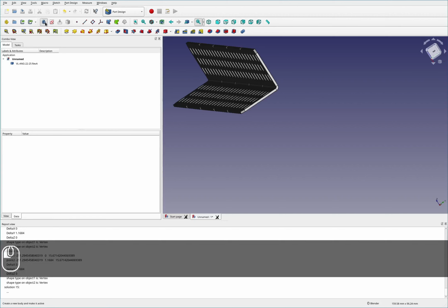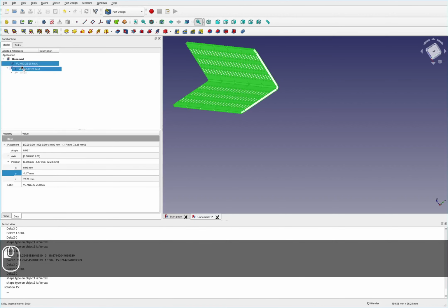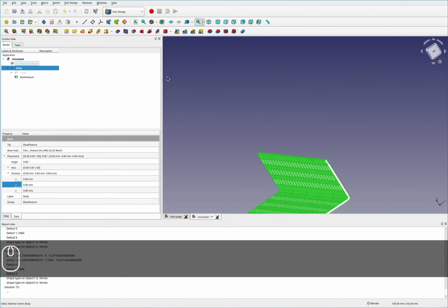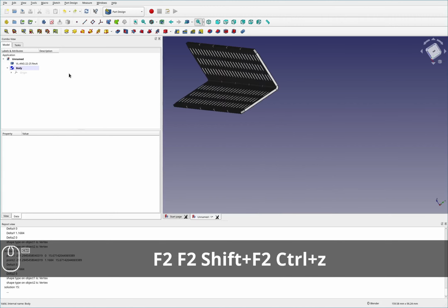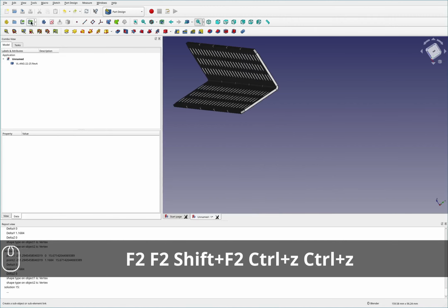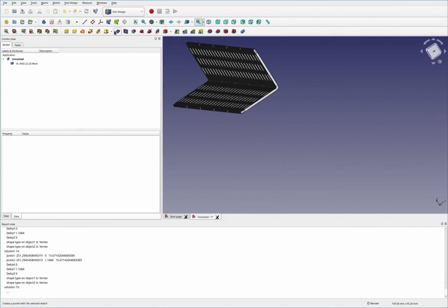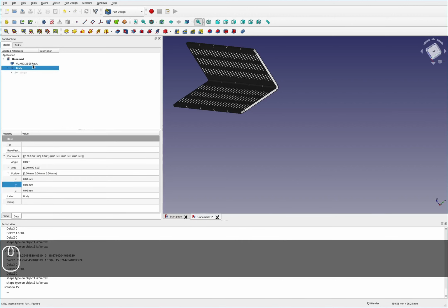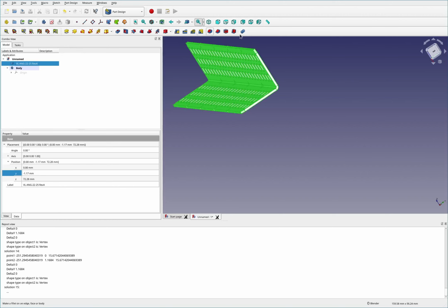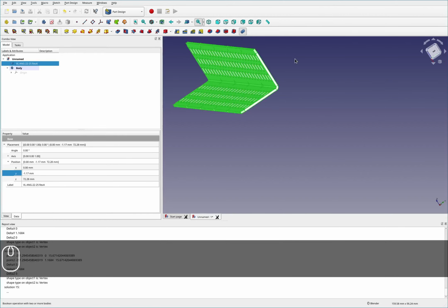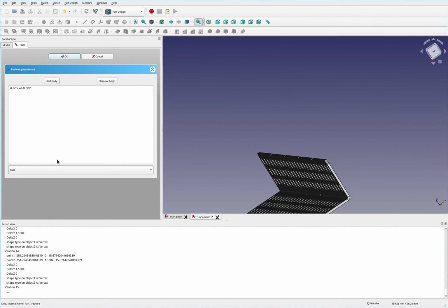And let's grab a body. We'll see if this part design object, yeah, so it ignores the translation we put onto this. So what I'm going to do to get around that is some kind of hacky bit, but I'm going to come over here and Boolean add this into the part design object.